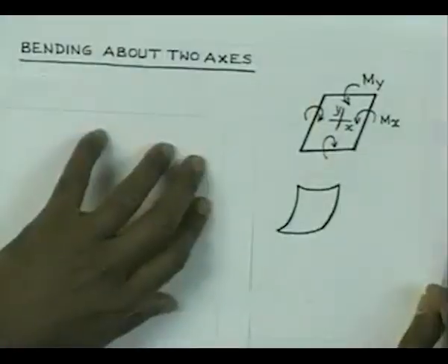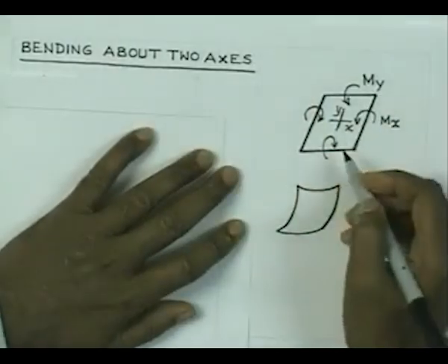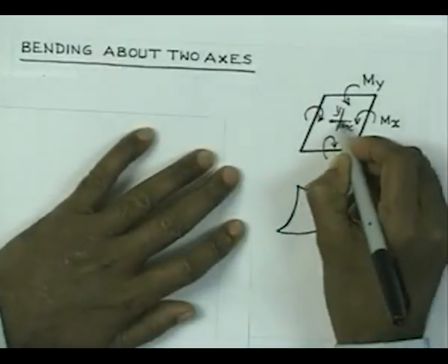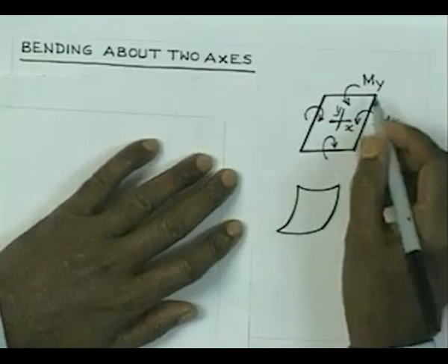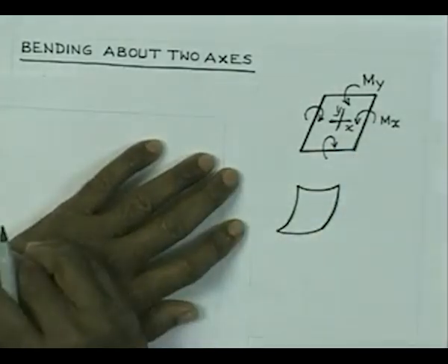Now, with this we can go ahead in deriving the moment curvature relationship in the case of rectangular plates. So, we have considered loading about one axis of the plate, we could as well have loading about both the axes. So, let us now consider bending about both the axes. We consider a plate like this, these are our axes, and this is as if the central plane of the plate.